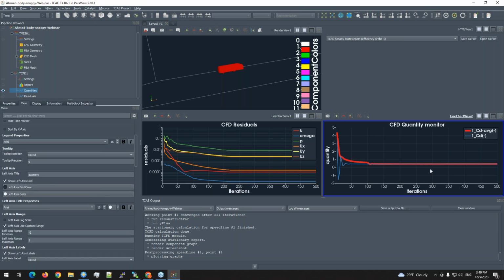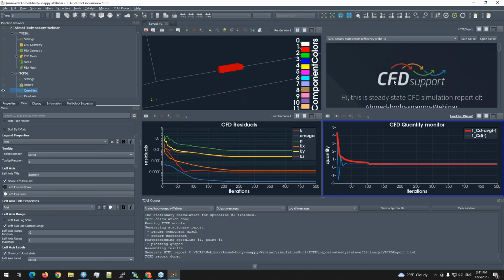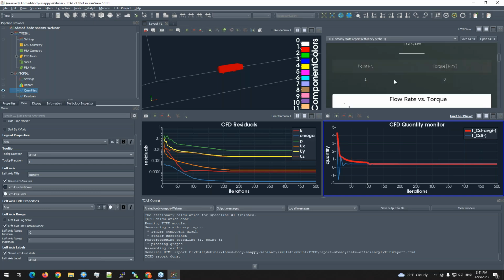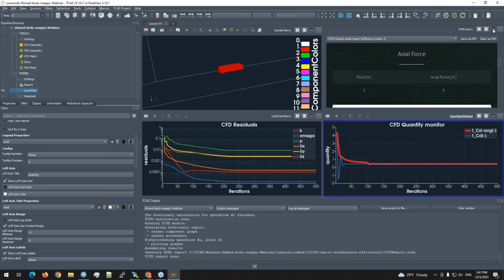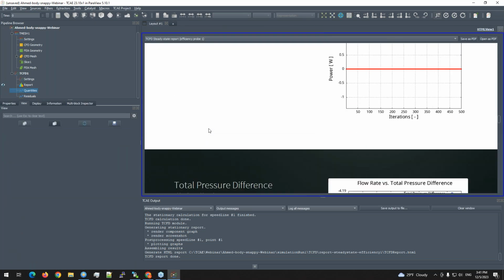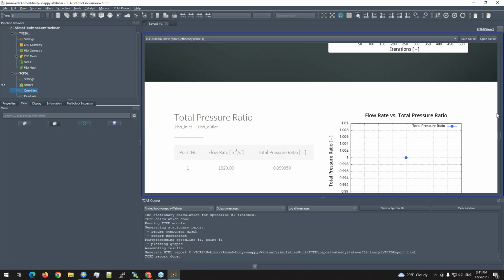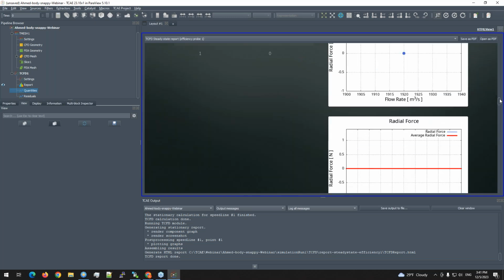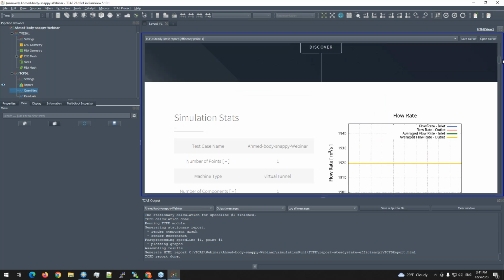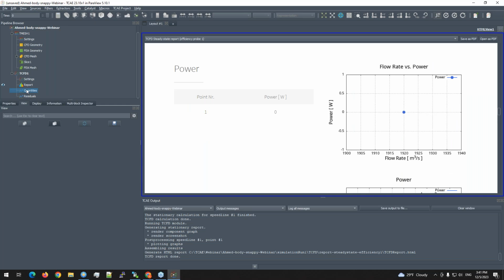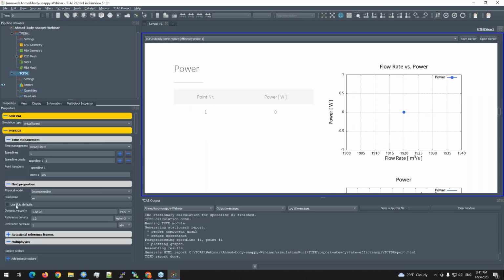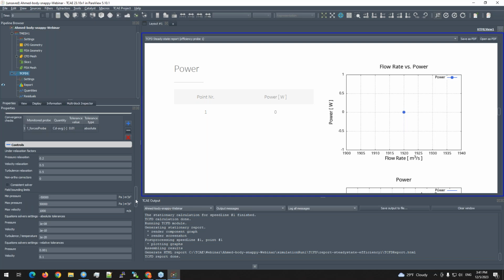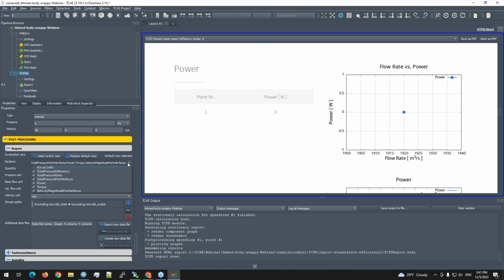And just to see the results, maybe we can wait for the final report, which shows us that the drag coefficient equals to, where do we find it, let's find the proper part, or maybe I missed. Okay, so let's go back to the TCAE, to the setup, to the report, and maybe I missed to check the most important part. Yeah, to enable these force coefficients.